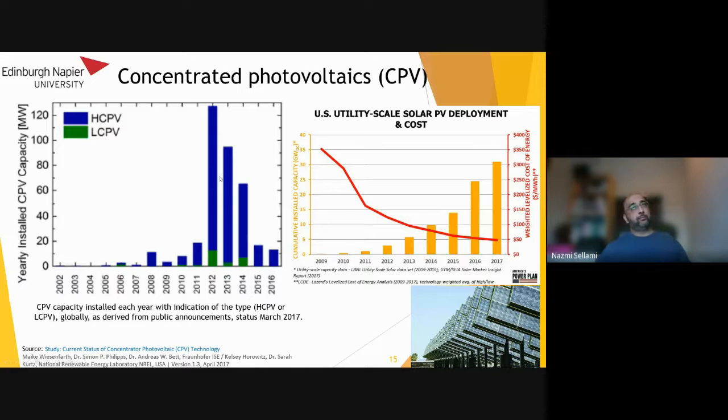Since then, it wasn't cost effective at all to use CPV because it requires a tracking system, a heavier stand and structure, and motors and maintenance, all these kinds of costs involved. So CPV lost the battle against conventional photovoltaics, the non-concentrated and non-tracking ones. Since then, practically there are only one or two companies still producing this, as I said, and the only application is space application.